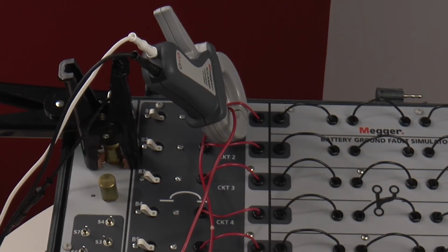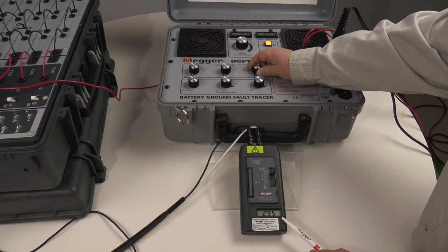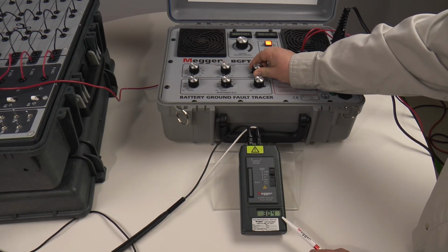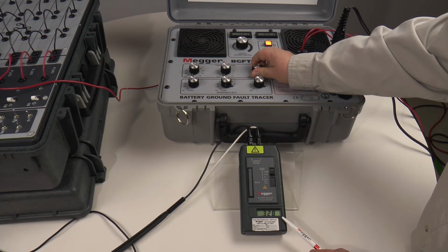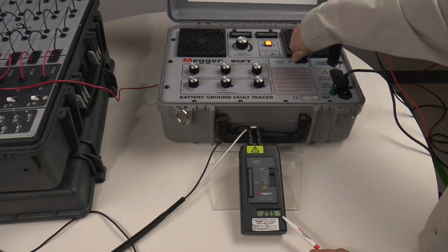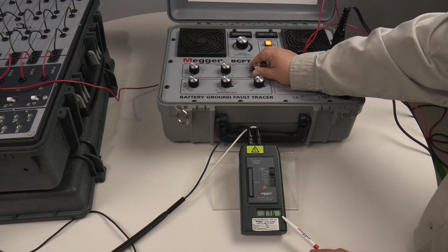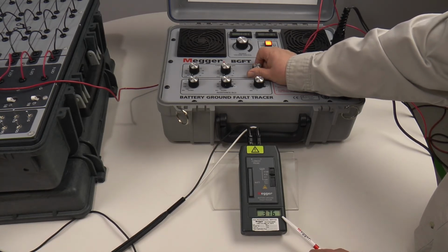So we place the CT with the feedback loop on circuit 1. Now, we will increase the capacitance on the Wheatstone bridge. Notice the reading of the receiver is going up, so we turn the feedback loop around. We see now it goes up with the feedback loop in either direction. This indicates there is no capacitance on this circuit.